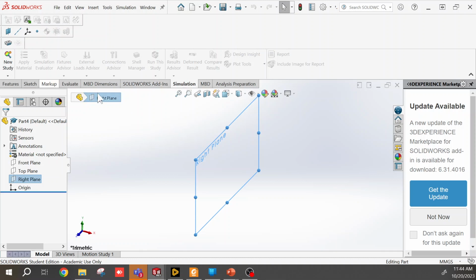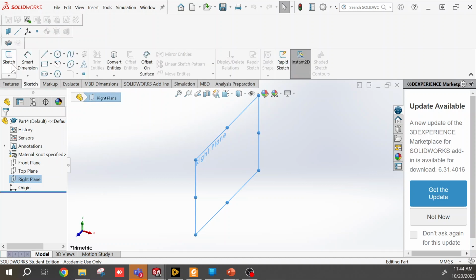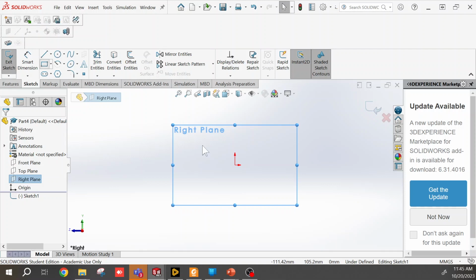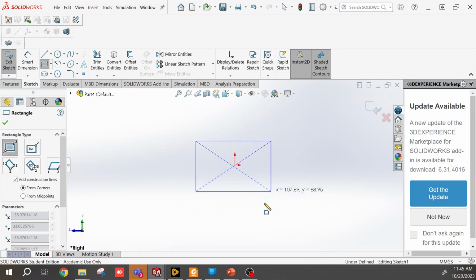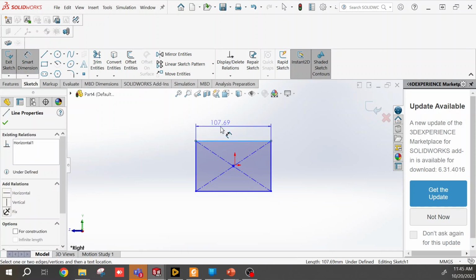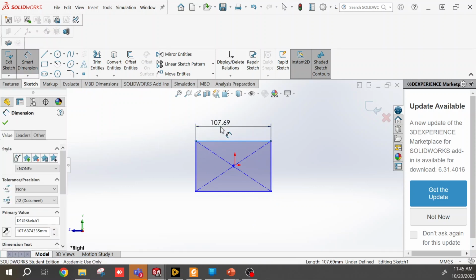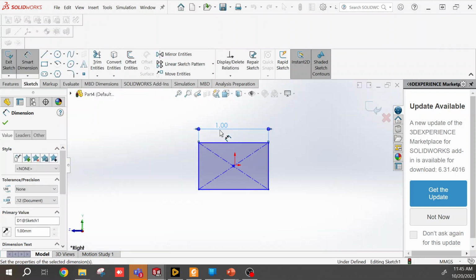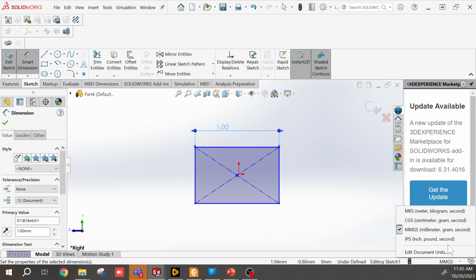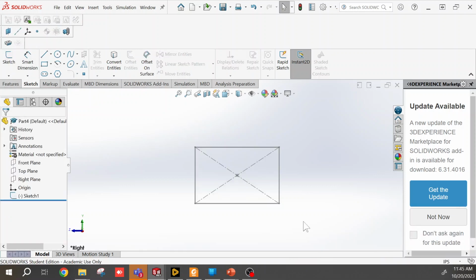So we're going to do a front plane sketch. And I'm going to go through this really quick because I'm assuming you know how to use SolidWorks at least a little bit. But all we're going to do is create a box here and make the side lengths 1. It's asking us to do this in inches, I think, so we're going to change the units on the bottom right here to inches, pounds, second.